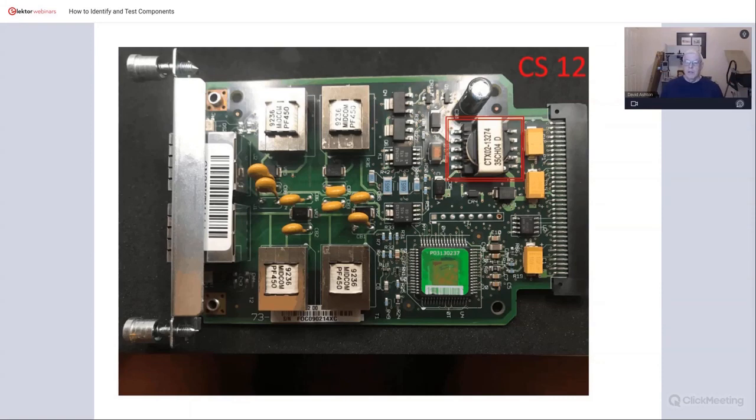So if you get your inductance meter and do a few tests on the thing, you'll probably find which windings are the highest inductance ones, and those will be the high voltage windings. And you may be able to use this in a little inverter or something.